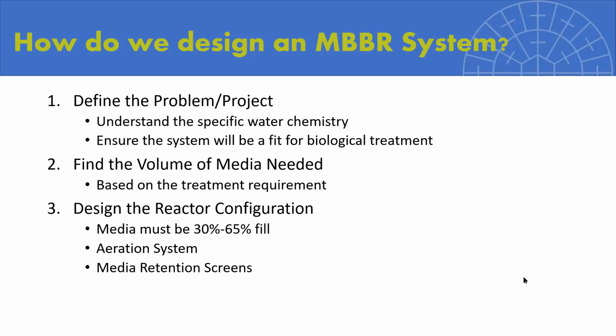Every single project is going to be different, and it's going to require a different approach to the design. It's really important not just to understand how much BOD you have, but to understand the plant holistically. What treatment do you have upstream, downstream? Understand the water chemistry holistically. Do you have enough alkalinity? Do you have pH imbalances? Is there any toxicity in the system? We'll dive into all of those a bit more in a second.